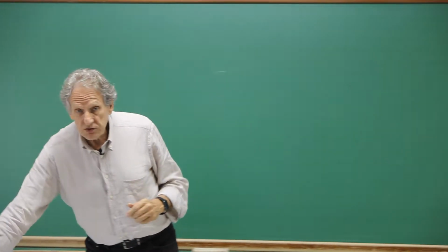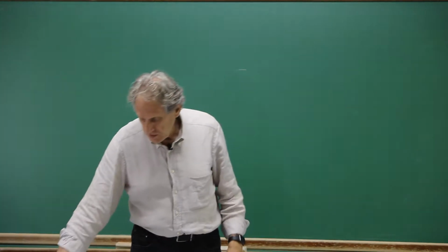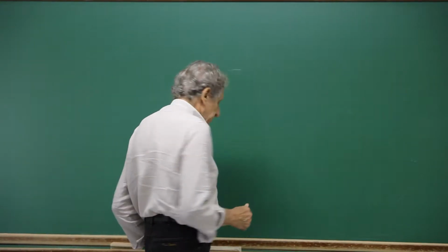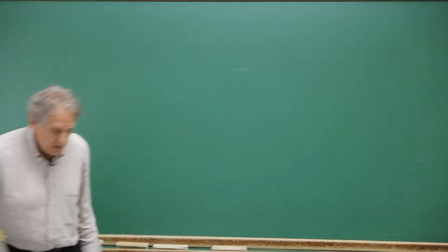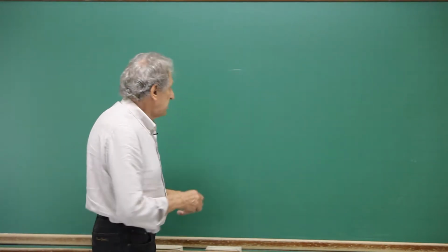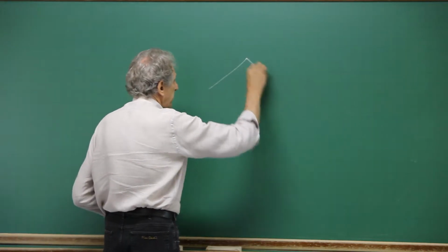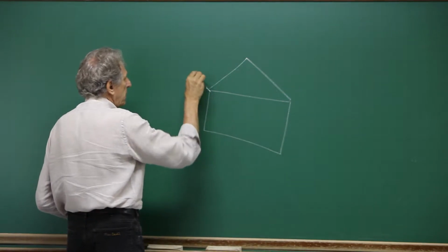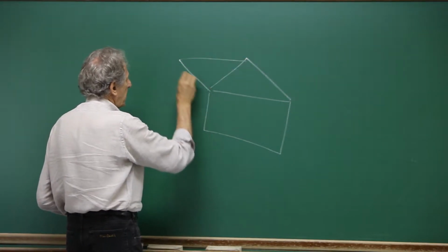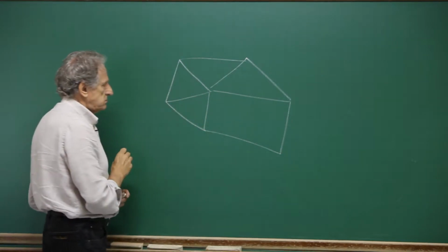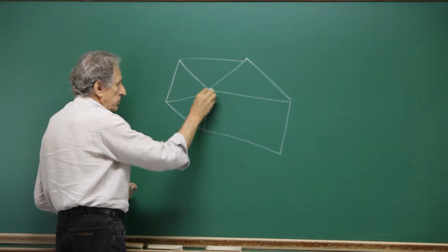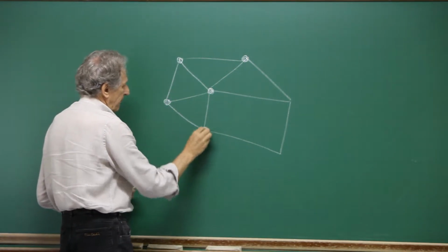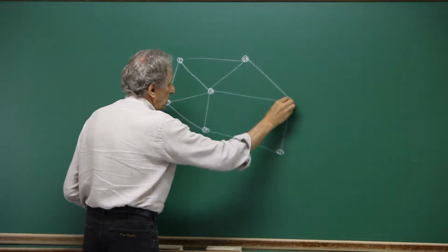So you can construct the control volume in different ways. The element-based finite volume method is constructed like this. Let's say you have the grid here, a mix of triangular and quadrangular elements. The unknowns are here, in the vertex of the element.